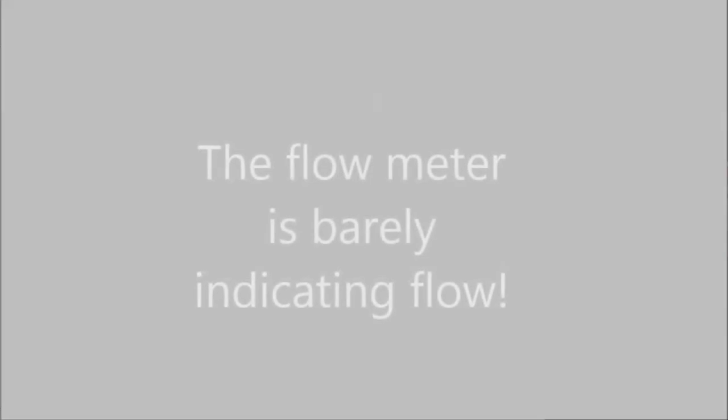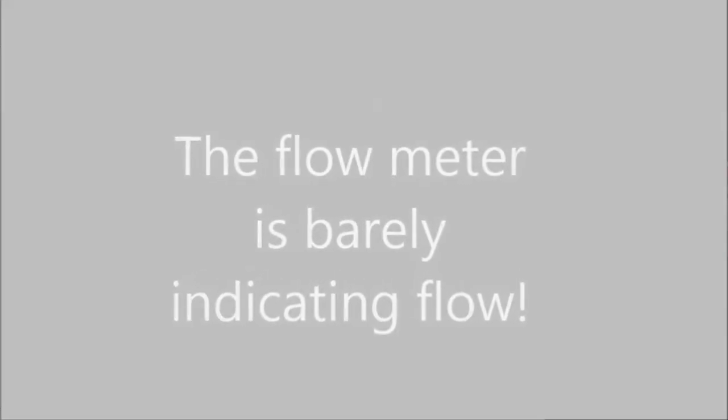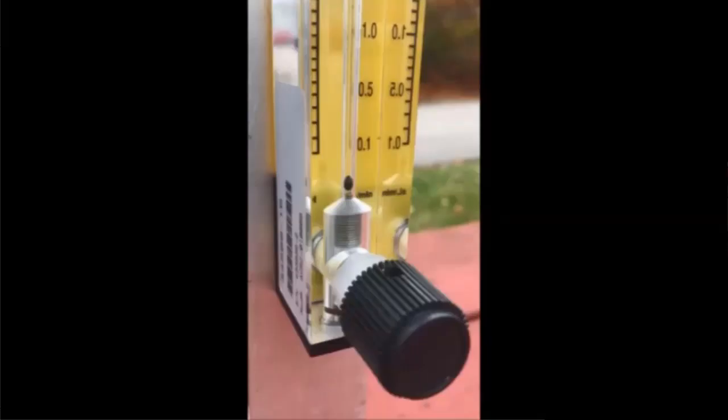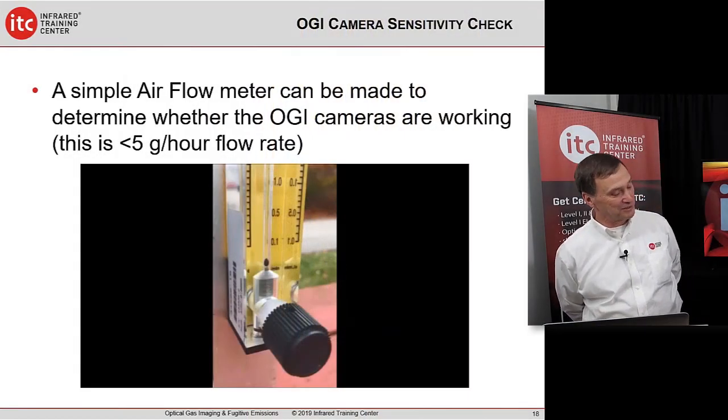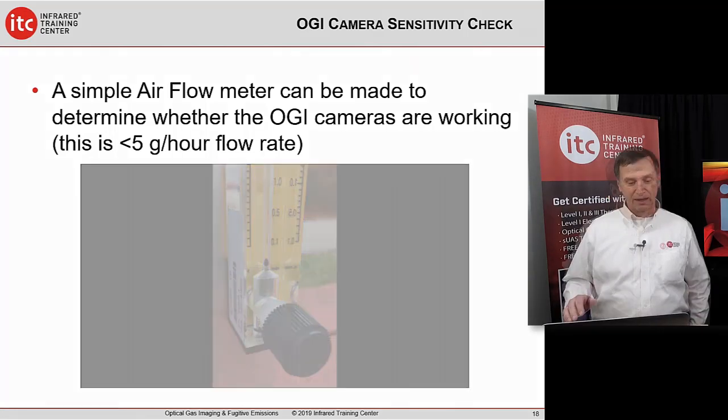But when you go into the high sensitivity mode, we'll really get to see the gas. And we have 8 levels of high sensitivity, which is a continuous image subtraction. The 0 would be for the very, very large leaks, the 7 for the very, very small leaks. As you can see, as that image degrades, the whole thing fades away. And that's just the time between failure. And that flow meter was barely indicating. You can get an idea, that little black bead there, as to how much gas was coming up. So these cameras are pretty sensitive.